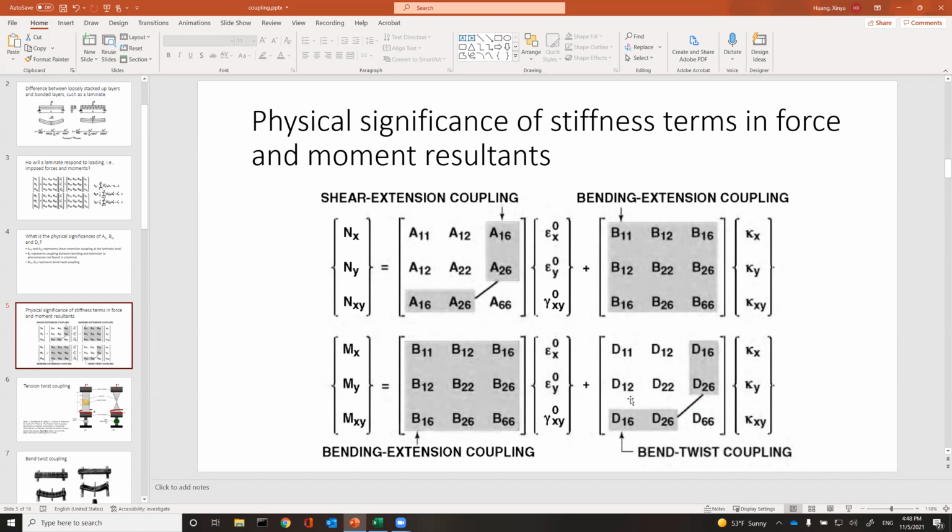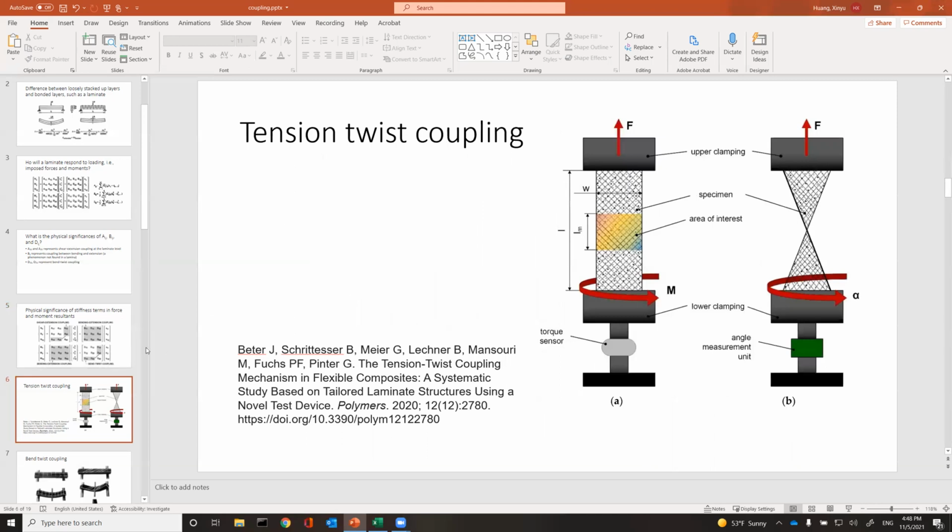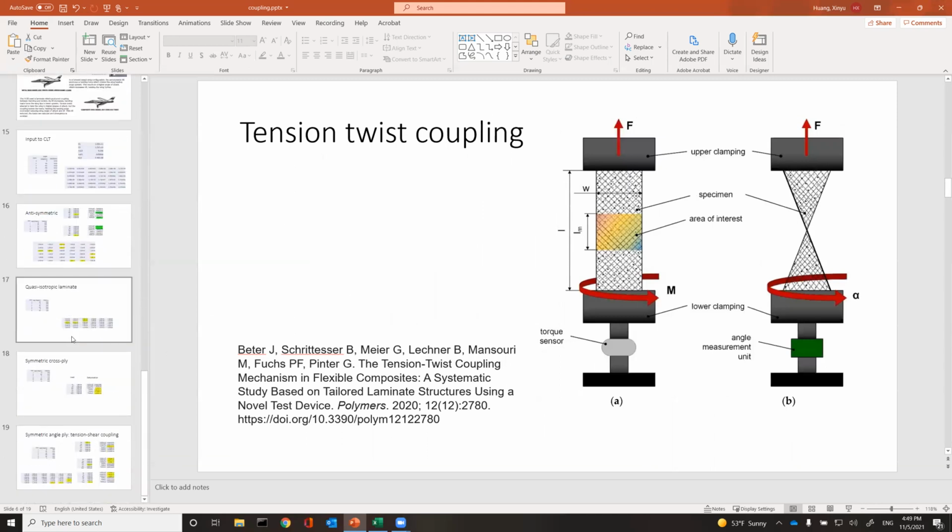And the D term is interesting. The D term basically is what enables the aeroelastic tailoring of the wings. It also has strong dependence on symmetry. When you have anti-symmetry, the D terms are 0. Okay, that's a brief summary. If you're interested, you can play more with layups. I think that's what I want to play with today.